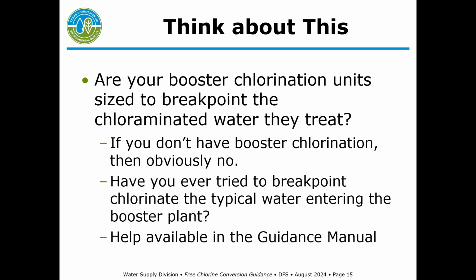One of the important things at some of these conversions: are your booster chlorination units sized to breakpoint the chloraminated water they treat? In general, I'm talking about your purchase system, or you've got a booster plant. You've already got chloraminated water coming in. You've got to add enough chlorine to breakpoint chlorinate those chloramines. It's not as simple as saying our wholesaler is going to switch to free chlorine for us. They may, but if they're not,